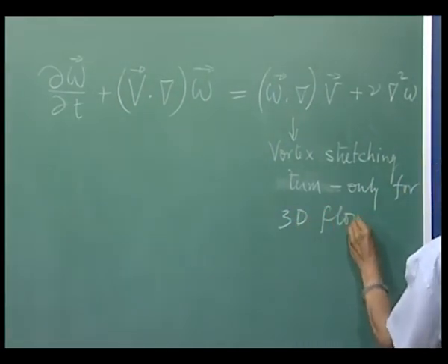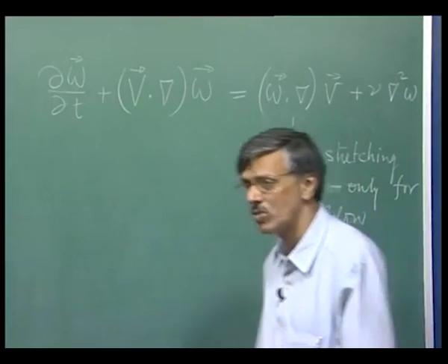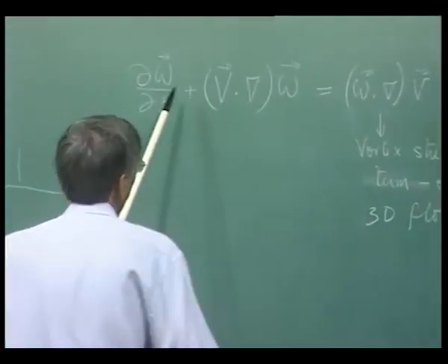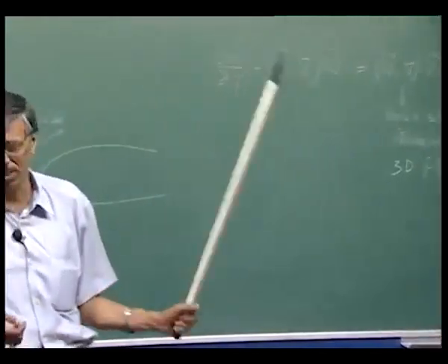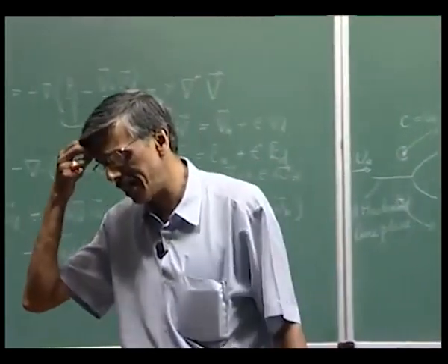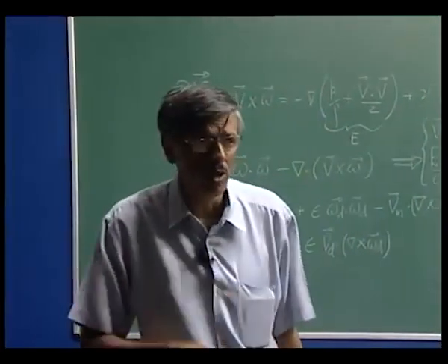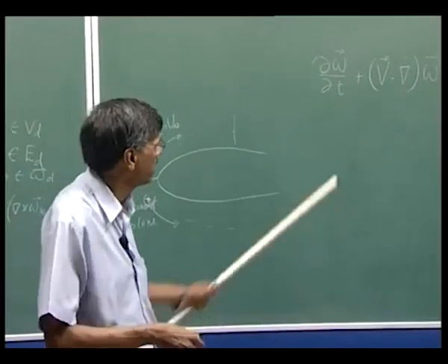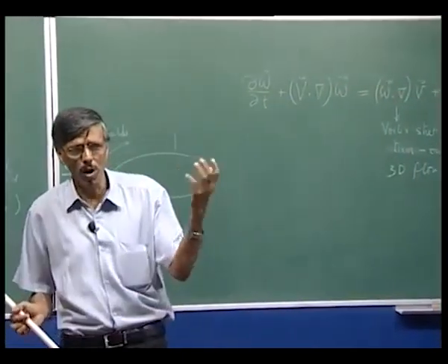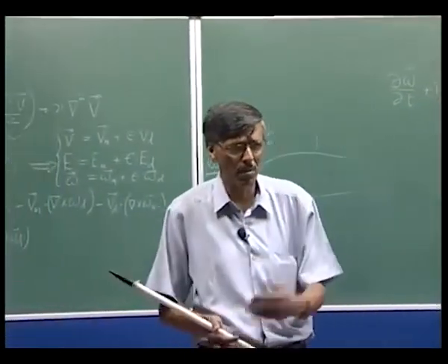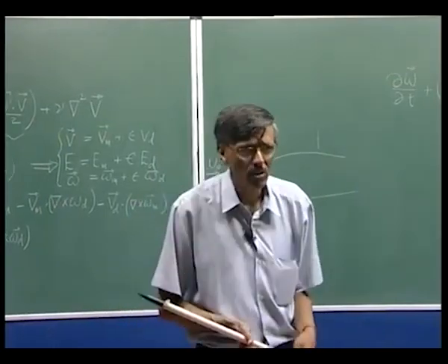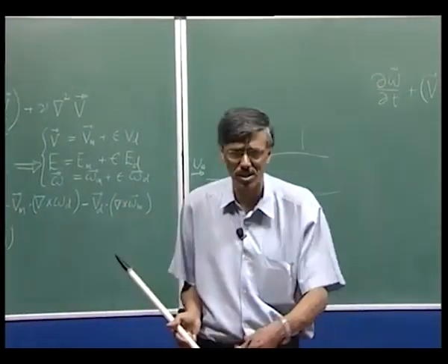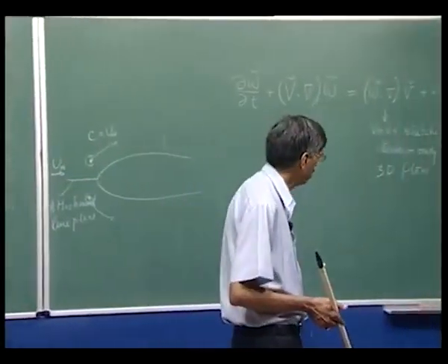And this observation, the splitting of vorticity transport equation in this form, was very elegantly used by Kolmogorov and his school, where they showed how energy cascades due to this nonlinear term from small values of wave number to large values of wave number. We'll come back to that discussion in the second part of the course.